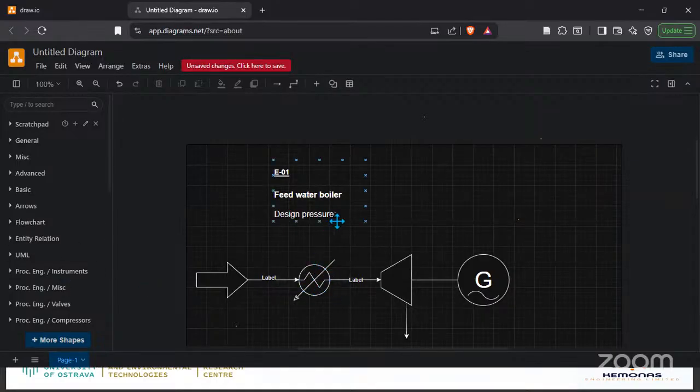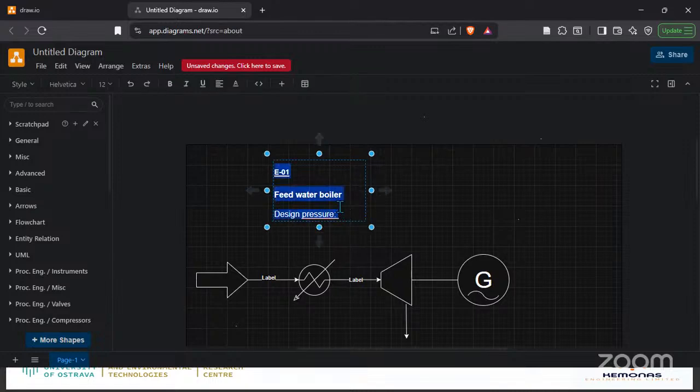So in this stage, we'll decide, okay, what kind of material should we use for the tubes, because they will need to withstand very high temperature. Otherwise, the tubes will what? Fail. There will be tube failure. And when we have tube failure, there will be water or steam going into the boiler combustion chamber.